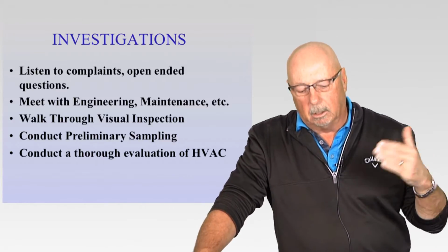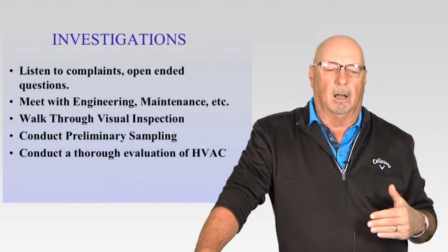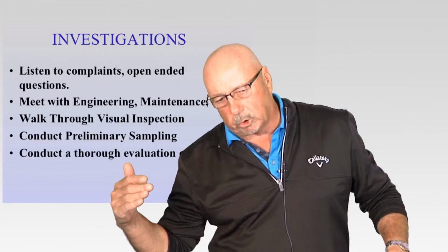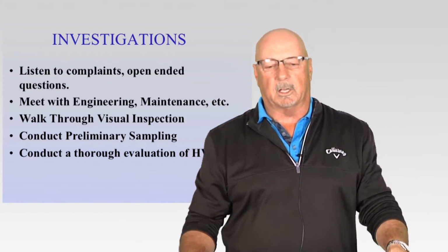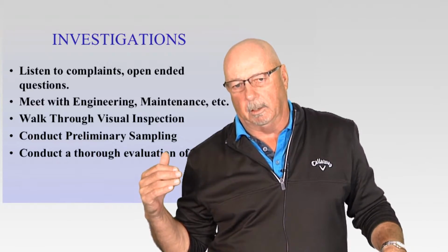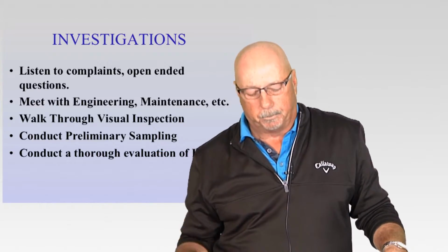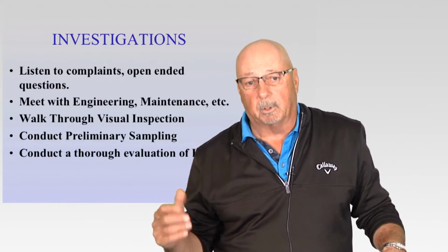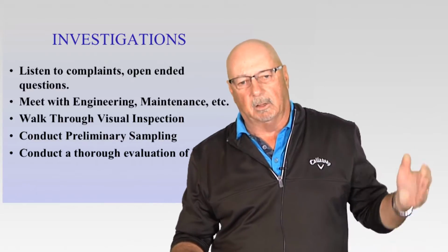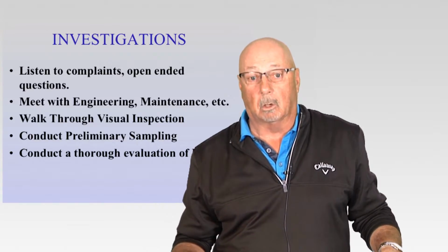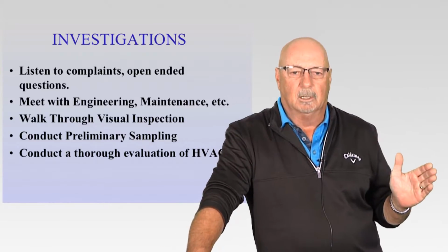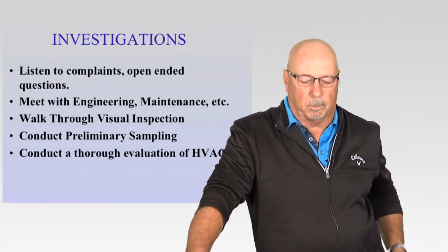And then go physically look, do a visual inspection of the various areas. Look at the mechanical rooms, look at the ventilation system, look at the filters that are being used. You'd be surprised how many times I've done indoor air quality investigations where the engineering or maintenance people say, yeah, we have our system set up to bring in 20% of outside air, and then we walk up there and we find out that the makeup air units have been disconnected and are totally closed. And so you wouldn't know this unless you visually conducted an inspection.